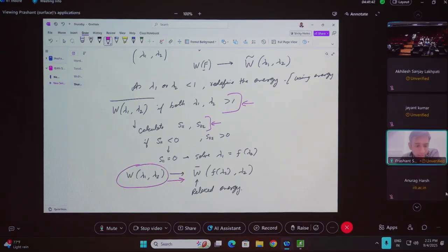Because if I keep on doing calculations with the usual energy, I would start to get negative stresses, and then my solution will be wrong, because a membrane cannot hold compression. And then you need to modify your theory or do something different. Okay?